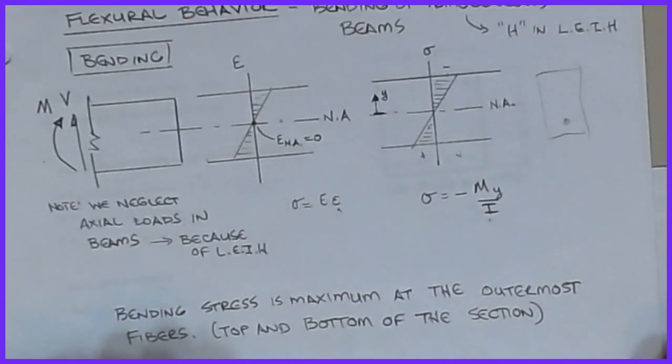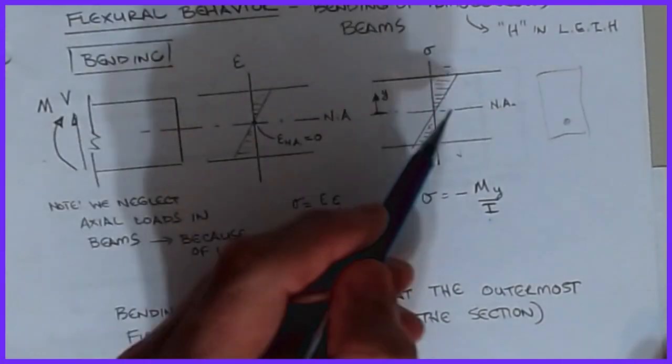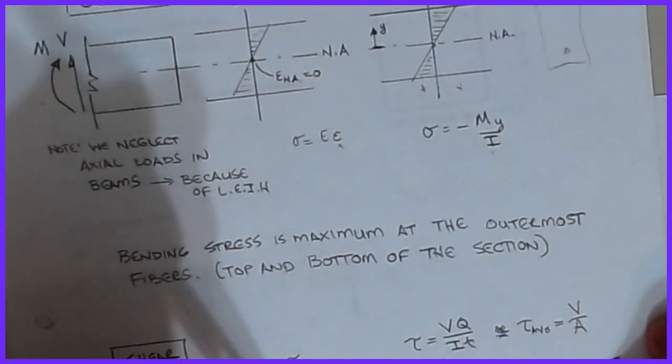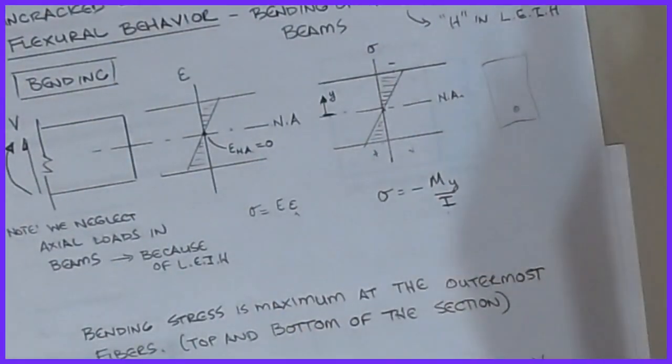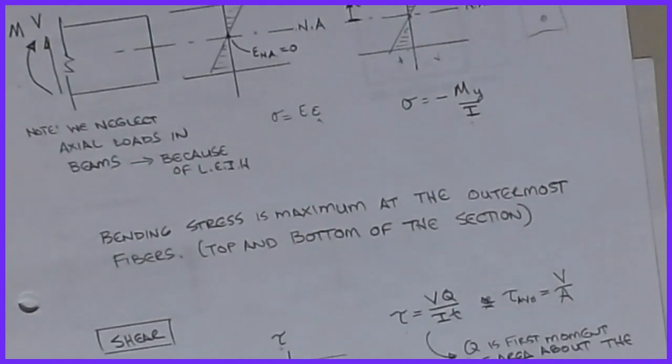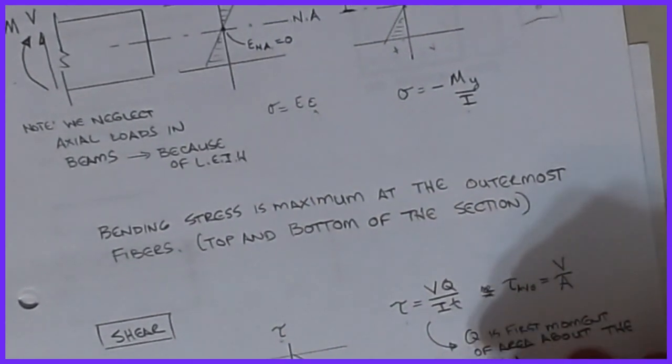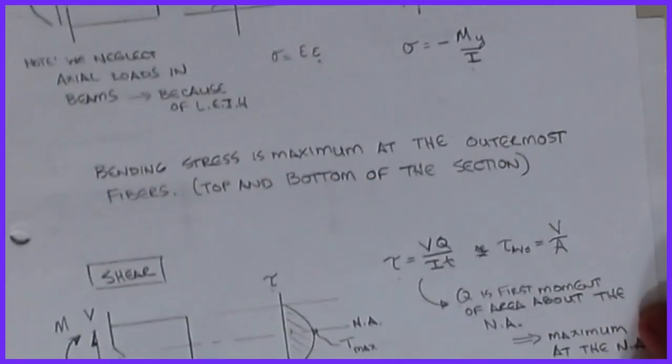So what you see is that the shear stress occurs as a maximum at the neutral axis location. Now compare that back to what you saw for the flexural stresses. The neutral axis was here at this location. What's good about this is that the location of maximum shear stress is a different point in the cross section than the flexural stress. So we don't get a whole lot of combining of the two effects. You do get a little bit, but for most purposes, they're pretty much independent.